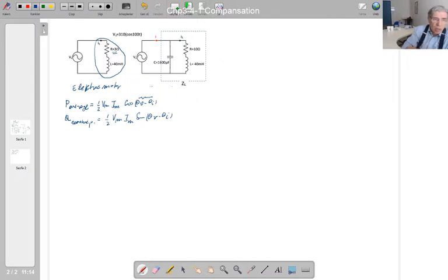Let's do this calculation now. If you consider now, theta V minus theta I is the angle of this impedance. I'll show it to you now. That is Vs. Let's consider that Vs as a phasor. V over I is equal to the impedance, isn't it? That is Z. What is this Z? It is the serial connection of those two elements. So it is 3 plus j omega L. So 3 plus j, that omega is that omega, isn't it? So that is omega.